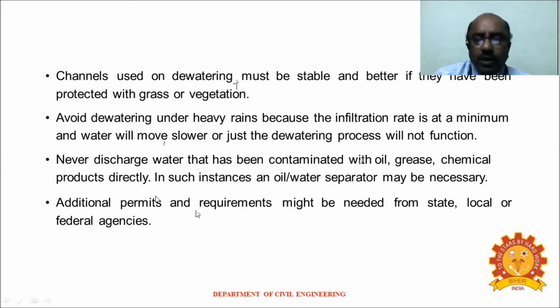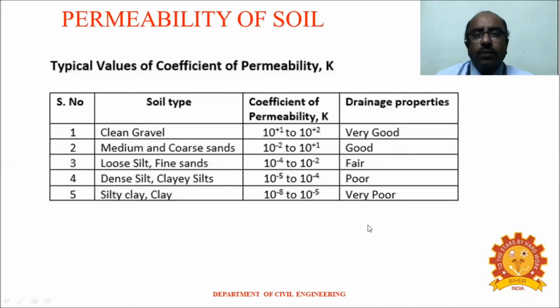And we have to get the permits and requirements from the state or local agencies whenever we do this dewatering process. So knowledge of the permeability of the soil will tell us what type of technique we can employ for dewatering.